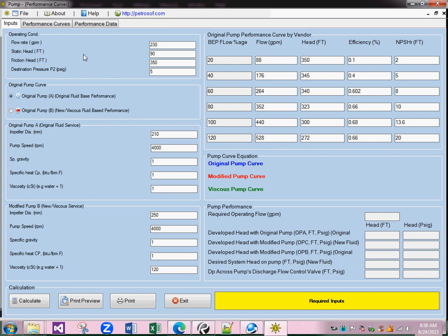So here, as I mentioned, the vendors or manufacturers mostly develop the performance curve of any pump based on a reference fluid, and in most cases they use water as the reference. However, sometimes they also use a different process fluid or a viscous fluid, other than water, to generate the original performance curve, which can vary with your site-based fluid process condition or physical properties.